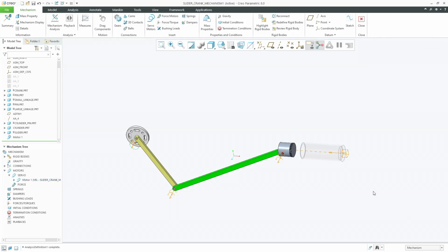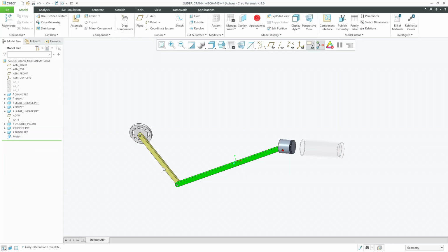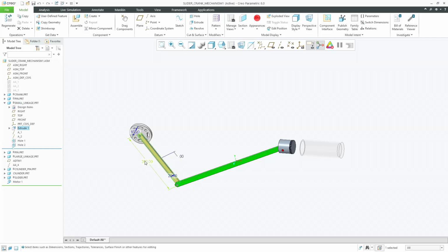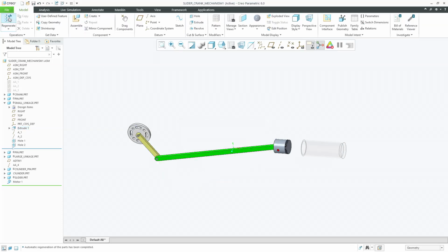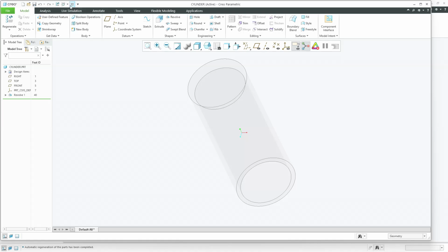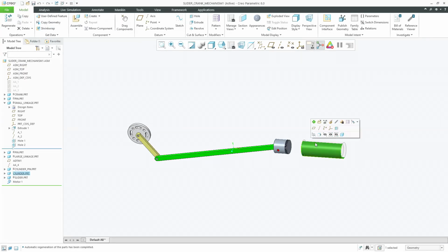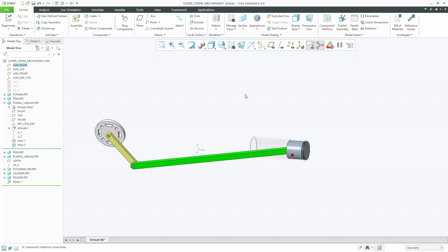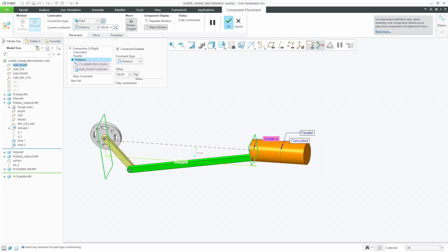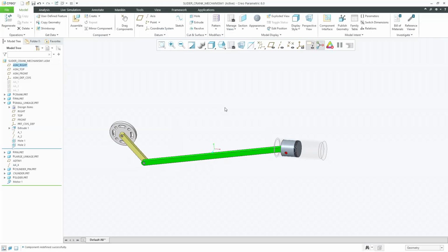I'll just close this, move back to the part level, select this smaller linkage and reduce its length. I'm going to halve the value of this, to 150, and I'll just click on regenerate. The entire system will get regenerated automatically. And also I'm going to modify the dimension constraints of this cylinder to 500 mm and just click OK. Okay, it's hitting the edge of this, so let me make it 600 mm and just click OK.